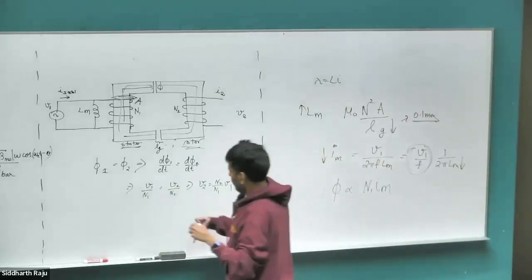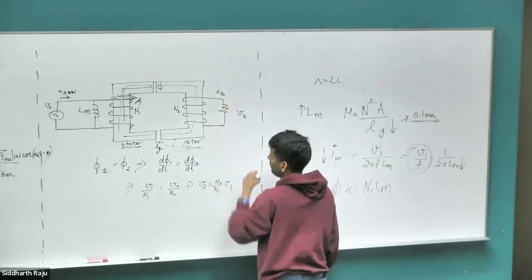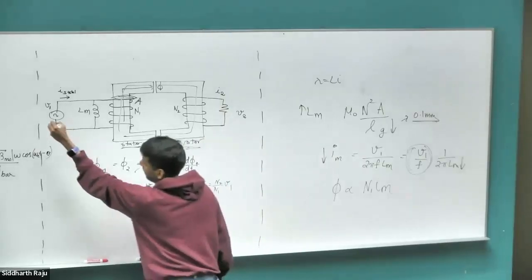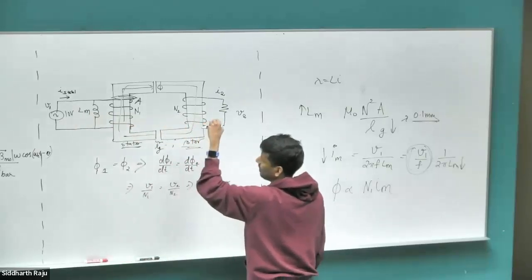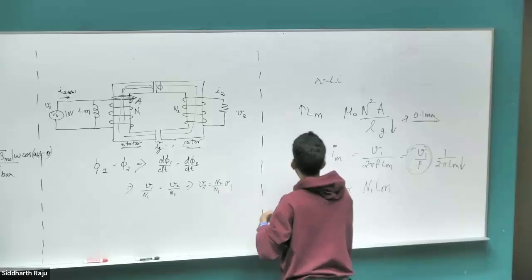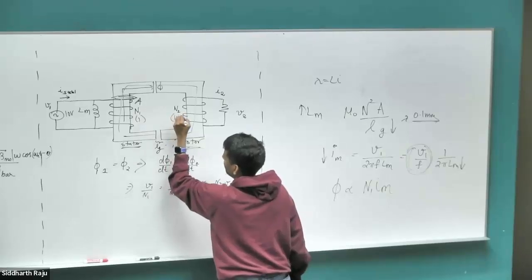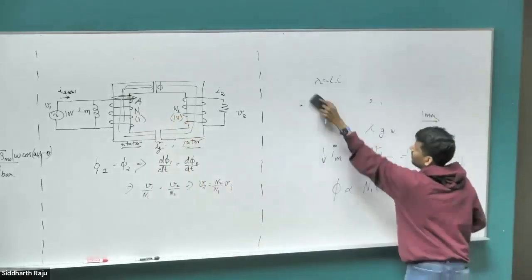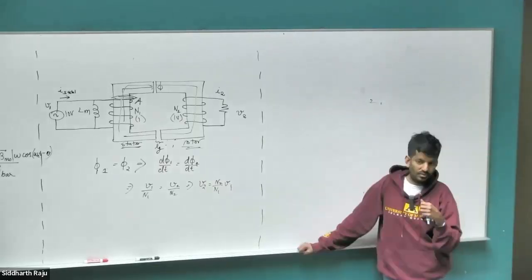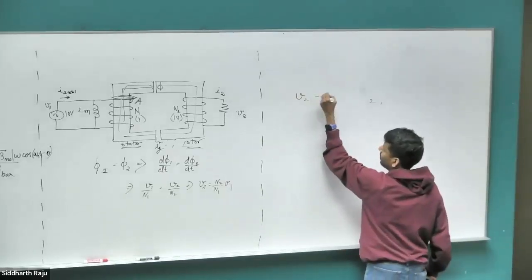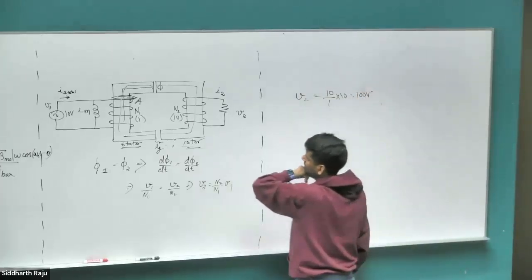Okay, so coming back to a transformer, let's now introduce some load on the side. And let's start giving some values. Let's say this is 10 volts sinusoidally varying at some frequency. And what is going to be my voltage V2? Oh, I need to give you the numbers. Let's say this is turns of 1:10. What's going to be the secondary voltage? 100. Just a step up transformer. 100 volts. Let's say the resistance here is 100